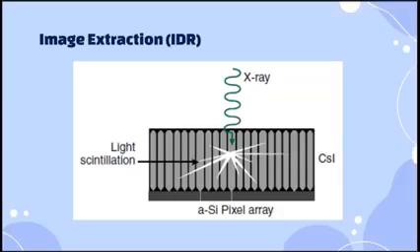And then, the light from the scintillation layer is directed towards the detector elements in the active matrix array below. Okay? By using amorphous silicon as a detector element, these DEXELs effectively become photodiodes, which convert light into electrical charge. So in indirect DR, meron din silang TFT array, active matrix array, okay, in their detector element.